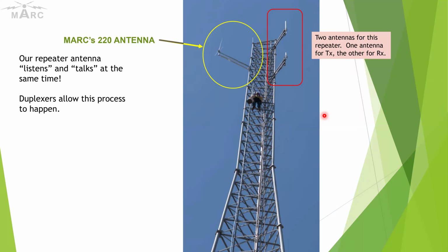They also have duplexers. And so the question is usually asked, well, Dan, you just said that if you're running a single antenna, you need duplexers. Well, these people are doing 2 separate antennas. Why do you need a duplexer? Well, these antennas are really close together. And if you didn't have the duplexers to do the same thing that it's doing with our single antenna, you would overblow the front end and do all kinds of fun stuff, right? So, yeah, they have to have canisters as well, even though they have separate antennas.